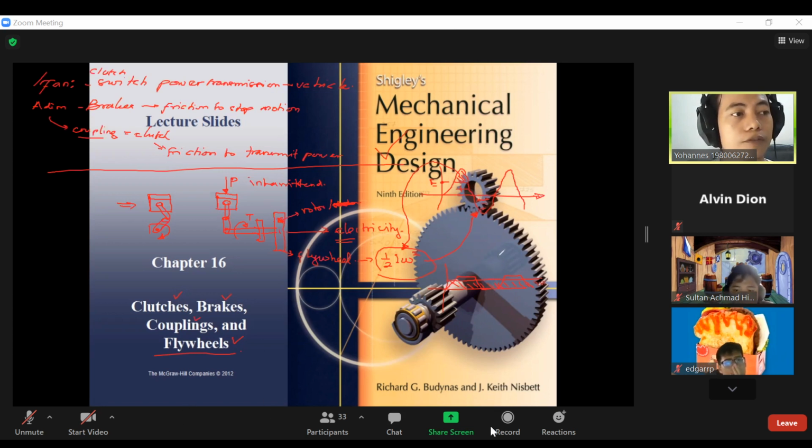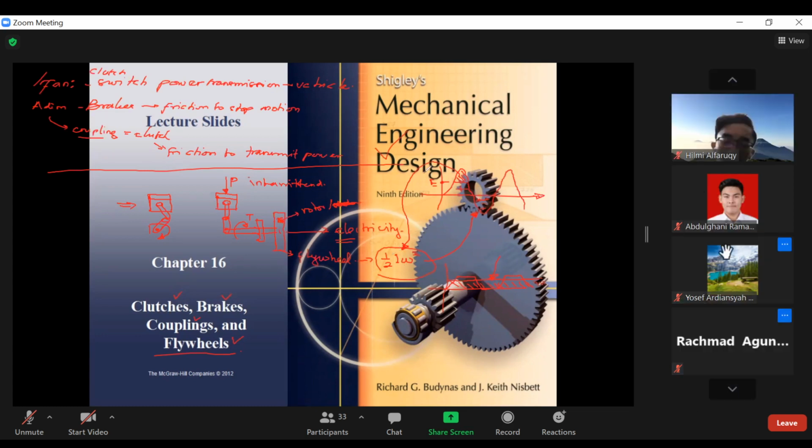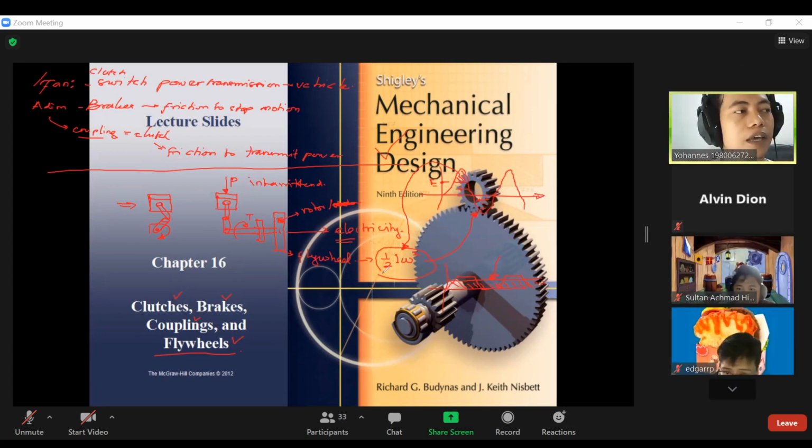So that's what you got from your vehicle, because you put a flywheel with enough inertia to absorb the excessive energy, then apply it when the mechanism requires more energy here. Okay. So that's the function of the flywheel. So the design focus on this flywheel is about how we can absorb the required energy using the appropriate inertia. Okay.